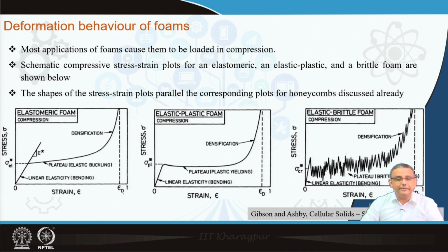But in the case of elastomeric foam, it is to be remembered that this deformation behavior is continuously elastic in nature, but it is not linear elastic anymore, it is non-linear elastic. That means if you remove the applied stress, it will come back to its original dimensions, but the behavior will not follow a linear straight line as per linear elasticity.